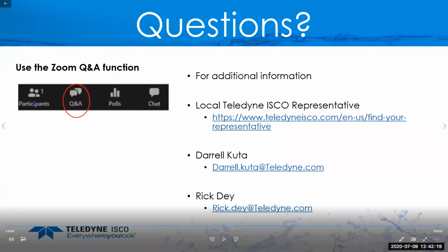And Rick, we got another question come in about what is the minimum depth of water needed for some of these sensors? And then there was a similar question about the level readings. So as far as the ultrasonic sensors, the range on most of them is 0 up to 4 foot or 10 foot. It depends on the sensor, but most of them can read level down to 0. But the difference is the amount of water you need to be able to read velocity.